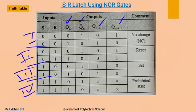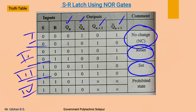For S 0, R 0, output will not be changed. For S 0, R 1, the output will be in reset state. For S 1, R 0, output will be in set state. And for S 1, R 1, output is in a race condition, so that should be avoided. Therefore, in the comment it is written as prohibited state.